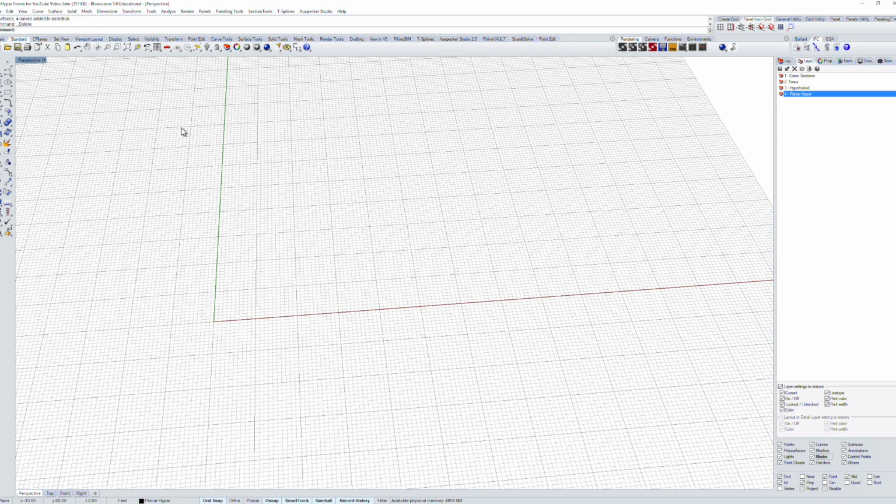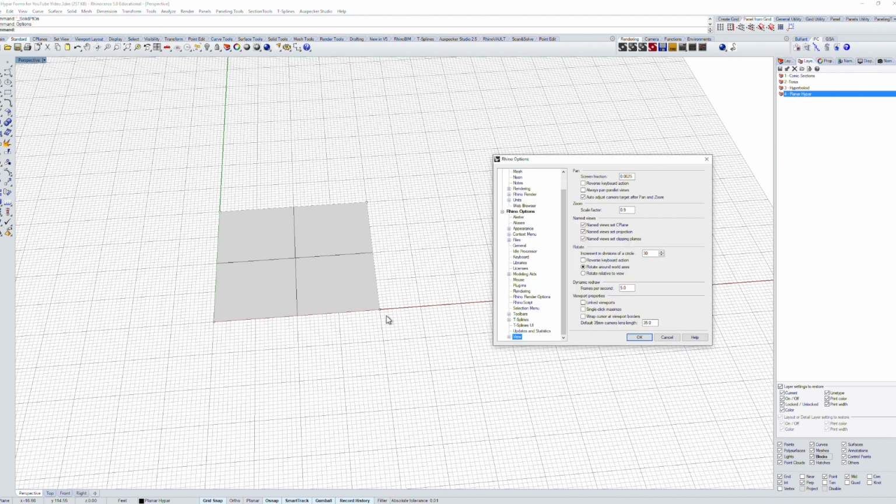One of the more interactive ways that I really like, though, is to start with a plane. I'm going to start at 0, and we'll go out, let's say, 40 feet on a side. And I'm going to turn on my solid points. So you'll find this under, and actually these are very hard to see, so I'm going to change my display properties here.